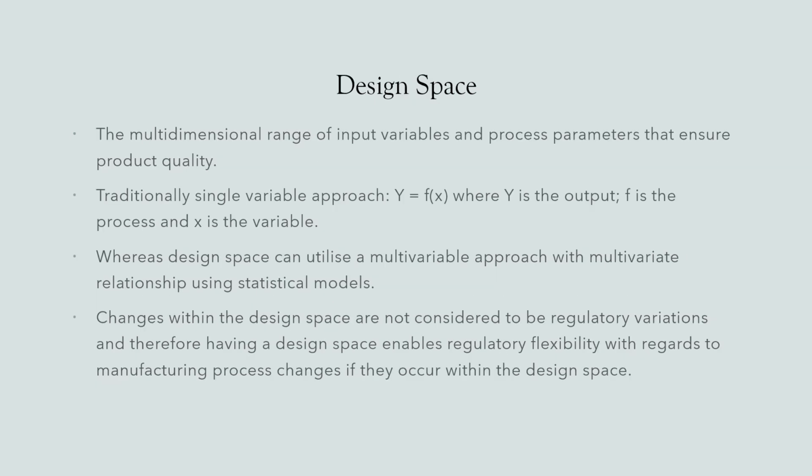So I just want to talk about design space. When we talk about design space, what we mean is the multidimensional range of input variables and process parameters that ensures drug product quality. What does that mean? Traditionally, when we think about the impact of, say, your drug product output and a variable, for example temperature, and the process that may impact it, we think about a single variable approach, yeah?